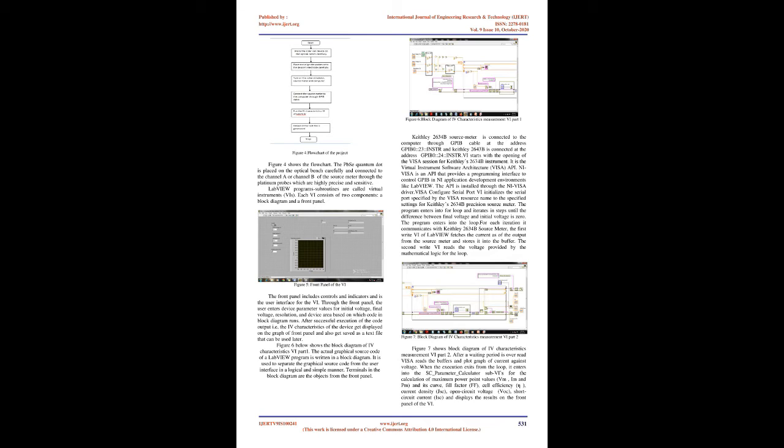Methodology. As discussed above, the three important parameters that characterize the performance of a photovoltaic cell are the open circuit voltage, VOC, the short circuit current, ISC, and the fill factor, FF. Fill factor is a function of VOC and ISC, so VOC and ISC are key factors for determining the cell's power conversion efficiency. Here we are concerned not only with the input wavelength but also the power of the input wavelength, so we must consider two different spectra, AM0 and AM1.5. Air mass is the direct optical path length for the sunlight coming through the Earth's atmosphere.